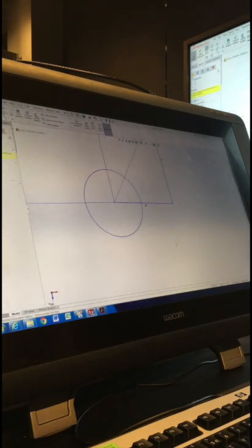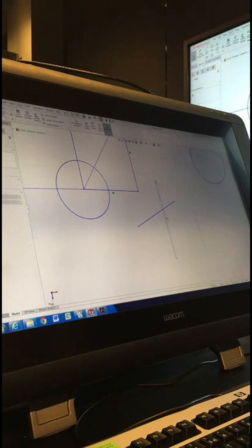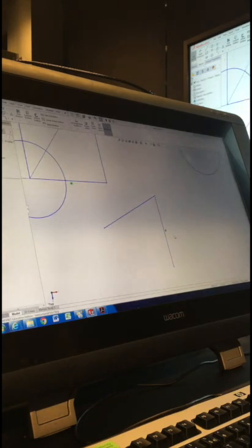So if I have a line that's just sort of in space with no relations on it, I can click an endpoint of that line and I can move it around to any angle. But if a line like this has a vertical relation on it, I can't change the angle of that line. It's always going to stay vertical. Now, that's only going to stay vertical while it's got that relation. If we've drawn a line like this here, and I actually want to change the angle of it, and don't want it to be vertical, I don't have to delete the line, I just have to delete the relation. So I can just click on that little relation icon and hit delete on the keyboard, and that'll remove it, and then I can change the angle of that line.